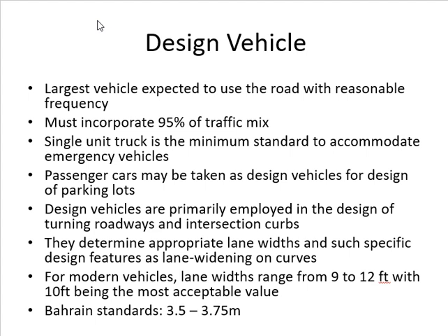Why? Which vehicle has the size of a single unit truck? Bus. So why would I take it for design? Why is it necessary to take a bus for design? It's a street, let's say. There is no bus. Which vehicle do I have to accommodate in my design? A passenger car is not a truck, right? So I will take the passenger car as my design vehicle. Yes. In my design for the bus, I will cover all the things.